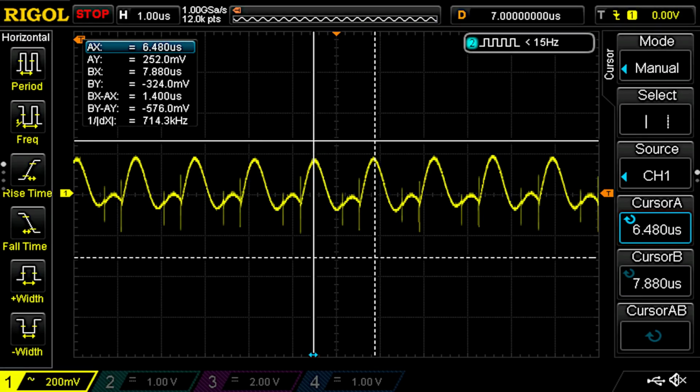Now with the proper inductor, the 12 volt rail right at the regulator on the display board looks like this. So much better. Frequency is up around 700 kilohertz, where it should be, and only about 400 millivolts on the 12 volt line. Probably would be okay, but I do want to put the correct capacitor in place. A 16 volt rated cap is not really good enough for a 12 volt supply. I do want it to last more than a year.